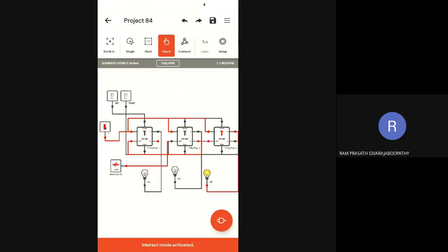Is it working? Okay, at the moment Srihari asked about T equal to 0. See, it remains in the last state where it got stopped. Whatever state it stopped at, it will hold. That's all. It is in the memory state now. Even though we are giving clock pulses, it won't change. When I enable the toggling, it will continue from where it left off.